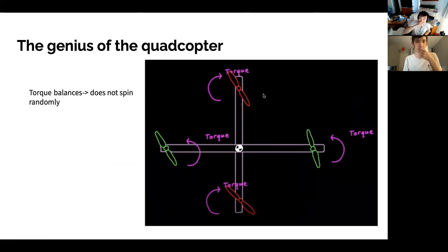And that brings us to the way torque works and the conservation of angular momentum on our quadcopter. So on the image on the right, you'll see that it's the same implementation on our quadcopter, where diagonally placed motors spin in the same direction. So like your front left and your back right will spin the same, back left, front right will spin the same, but each pair spins in opposite directions. And your motors actually have, I think, different colored wires depending on the spin direction. And if you plug them in backwards, then they'll spin in the opposite direction. So please don't do that.